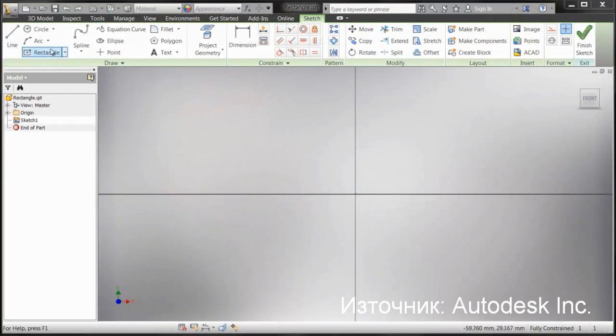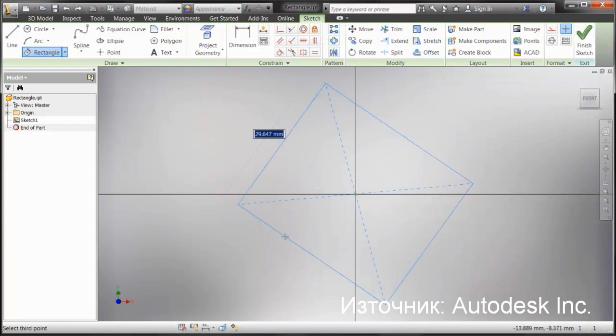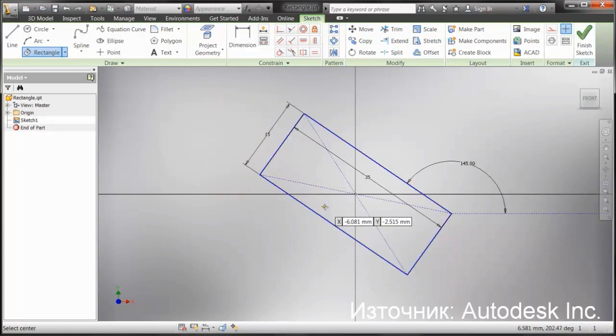Another way of creating a center point rectangle is with the 3-point center option. The user selects the center point of the rectangle as before. This time, the second selection changes the angle that the rectangle will be placed in, as opposed to just vertical or horizontal. They can then drag it to whatever they want, or key in any value that they need to. Once this is done, they can go back and change any of the values that they see fit.